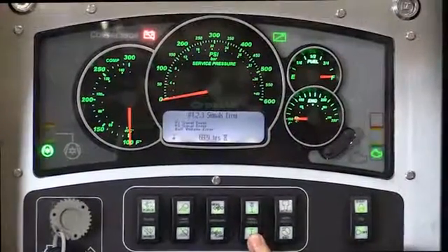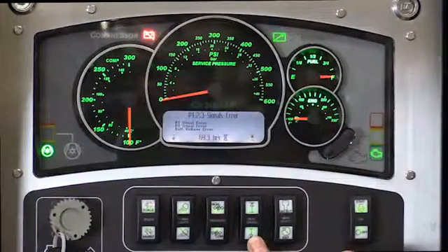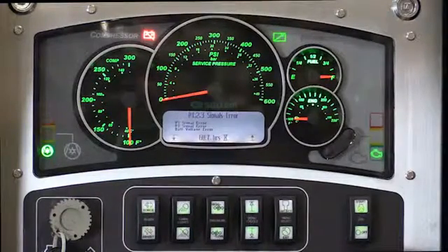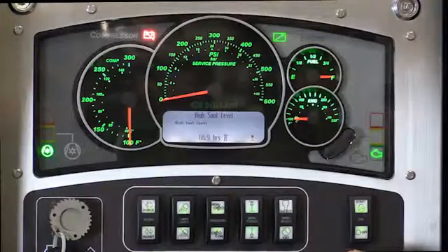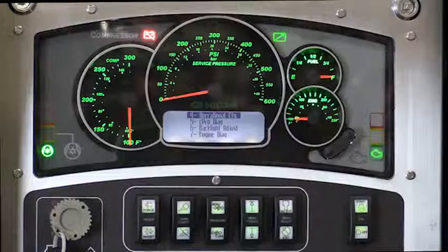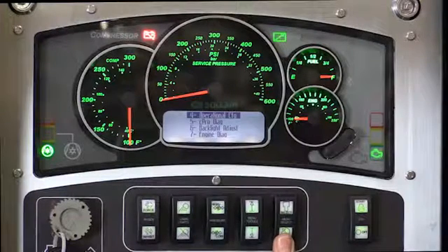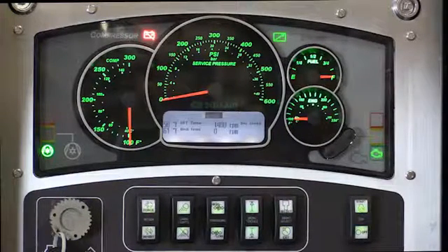Use the toggle switch to scroll up and down through the stored shutdowns. When you reach the view of the last shutdown stored, you'll notice that the arrow indicator will point up, indicating that you need to scroll up, that was the last one stored. As with the rest of the menu items, simply hit the exit toggle switch to exit from that menu. To exit from the Settings and Diagnostics menu, simply toggle the Select Exit button to exit.